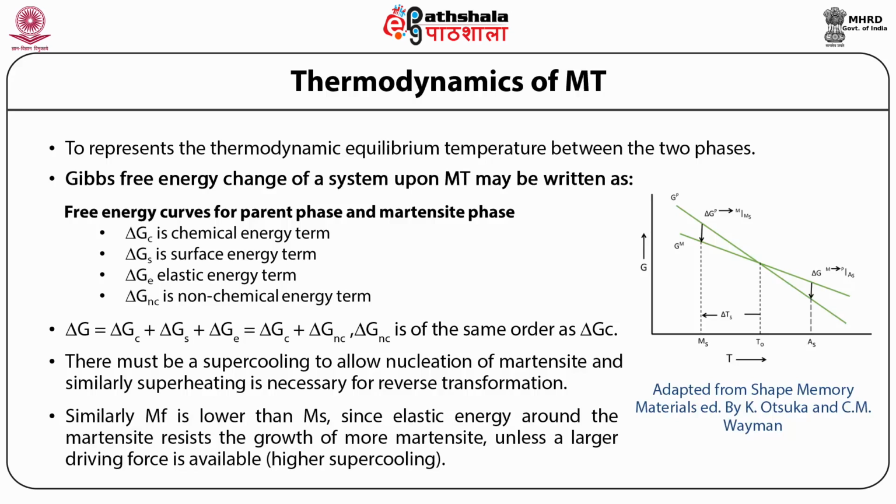Some rationale can be applied to the MF temperature, since the growth will always occur only to the extent that the driving force equilibrates with the elastic energy around Martensite.